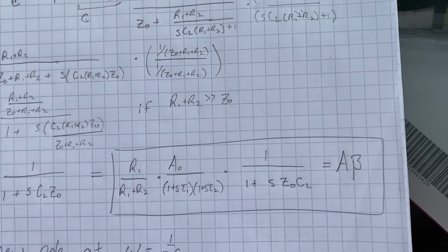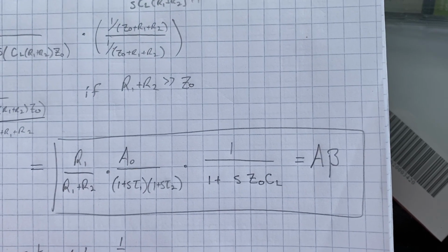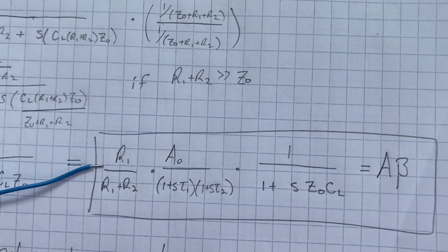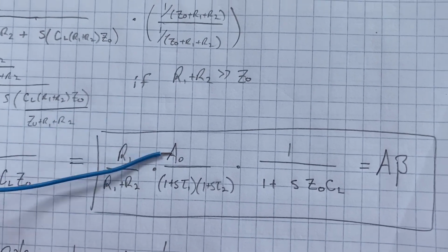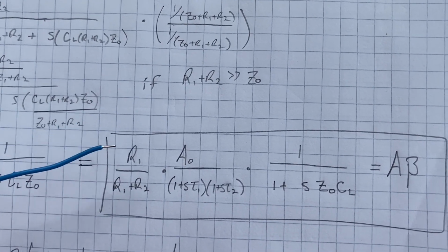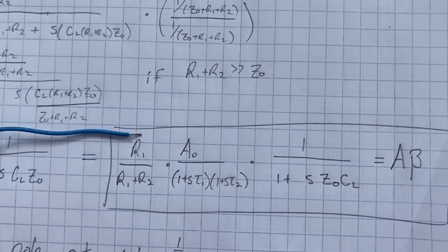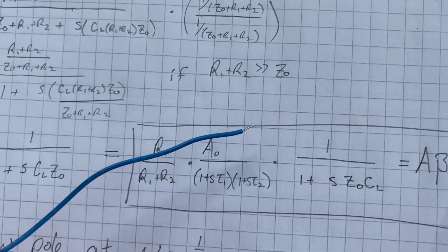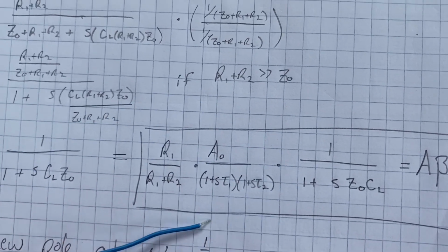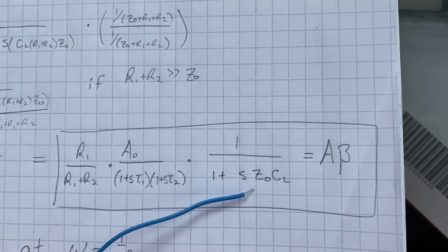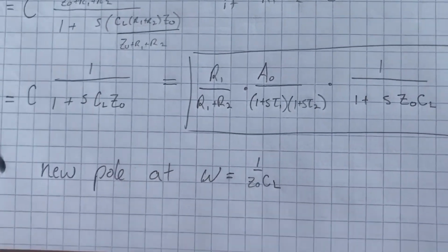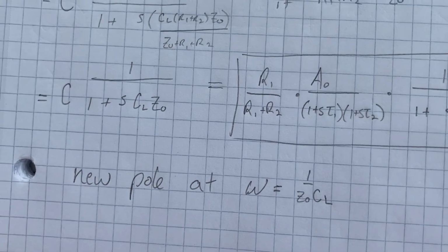But the final result is this, and we see that we have our closed loop gain we want, so 100 or 1 or whatever, determined by our resistors, our op-amp open loop transfer function, and everything here is just what we had before. But adding that capacitor, we add an extra pole to our loop gain, and that extra pole will affect our stability.